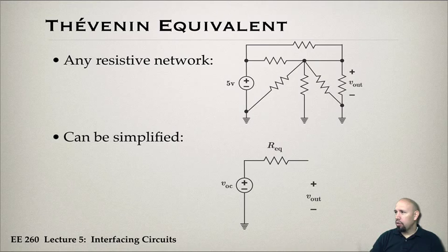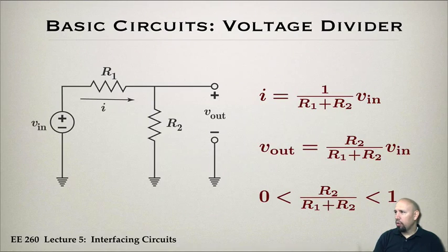So when we go back now to the concept of the voltage divider, this voltage divider then has that situation. And again, if you think of this now being R Thevenin, and we've connected now a load resistor up to that, then we're going to get a voltage division again. Okay, so remember, any circuit with sources and resistors and all that can be modeled this way as a voltage source in series with an impedance. So this is the R Thevenin now.